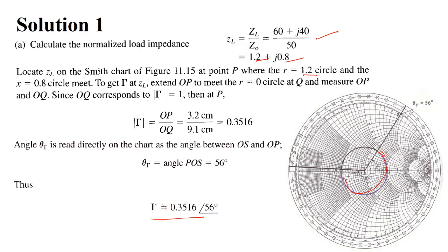If you have a transmission line which is mismatched towards the load, in general we have to match the load to the transmission line. So there it is very useful. You can use the Smith chart, and here you can find what the load should be, or what the section of a transmission line should be, and what type of stub you may use to match the load. Okay, so I stop it here.